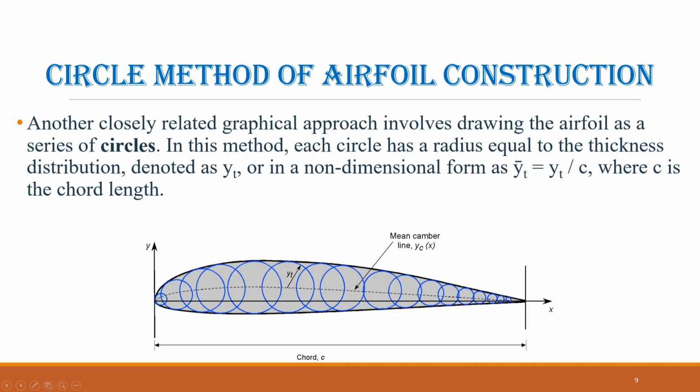This method is especially valuable because it provides precise control of the airfoil's leading edge curvature, which strongly influences airflow attachment, lift generation, and stall behavior. Once the nose is defined, additional points are plotted along the upper and lower surfaces to match the intended thickness distribution and camber line. The result is a smooth, well-defined airfoil that integrates all critical geometric features.